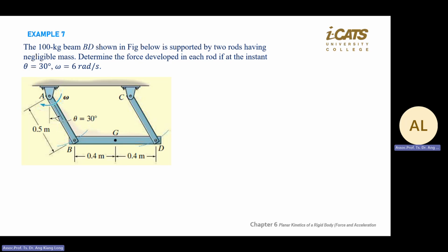How do you draw the forces at pin B? You always follow the connecting rod. And what do you feel? You feel something pulling you, if you are B and D, not pushing, not compressed. So it's like this one and this one.